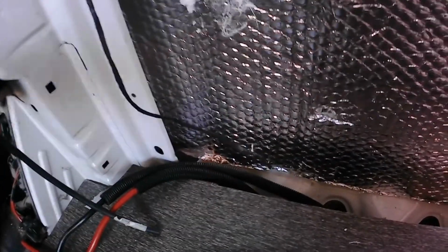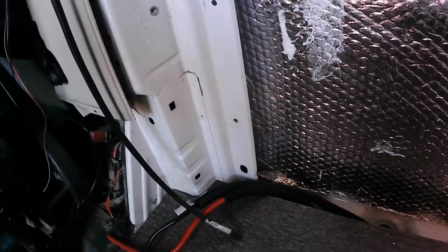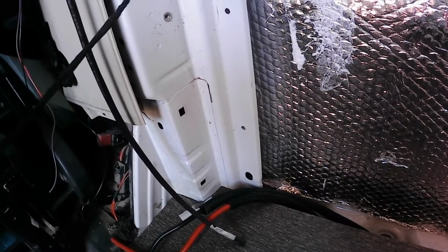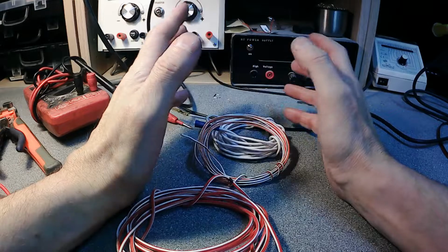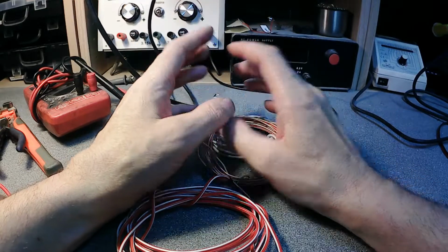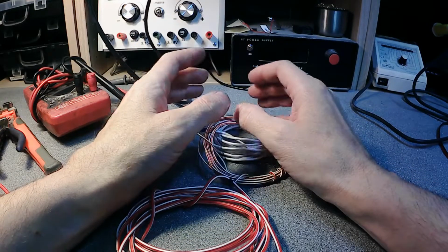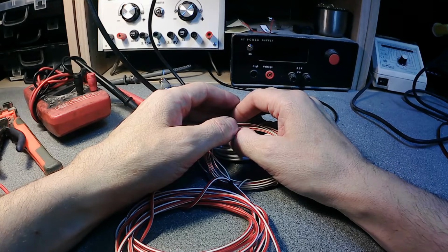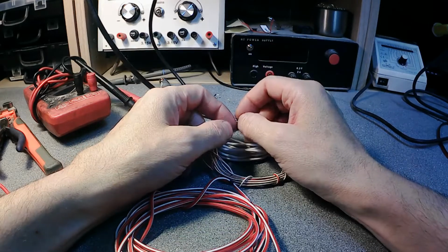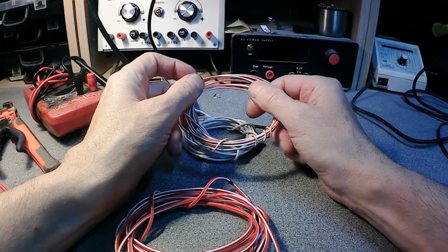Can we use one color of wire? Some people do wiring in only 2 colors. It's a simple installation: black for ground and red for live, and that will be enough. It's enough when you build it, but later on if you have to change something or repair it, it's a terrible job.